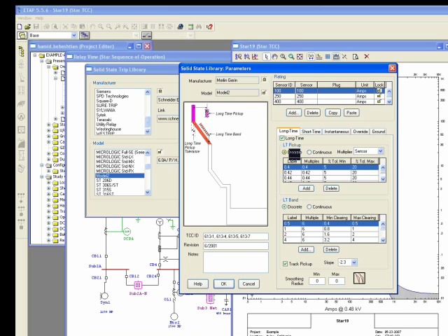Okay, this is my long time pickup, which is this area. If I change my long time pickup, the vertical section of this line can be shifted to the left and right because I'm trying to adjust my long time pickup.